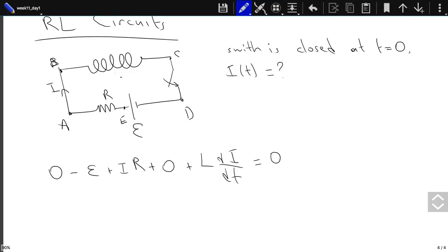Could you follow it? What we are trying to do is just consider the case when di over dt is positive. The current is increasing in this direction. If di by dt is positive, the inductor will try to prevent it. That is, it will try to run a current in the opposite direction to reduce this increase. But if it is trying to run a current in this direction, it just mainly means that this is at a larger potential than this one. So there is a potential drop as you go from B to C.